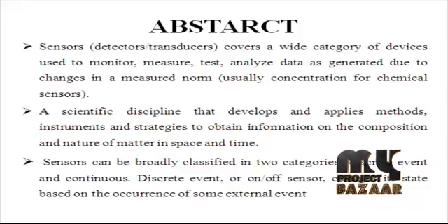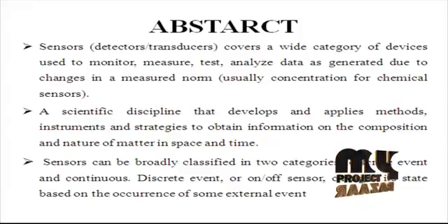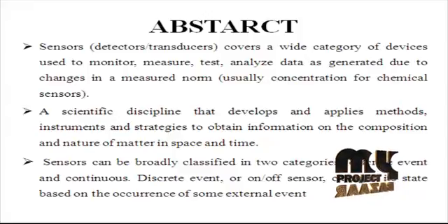Micromechanical resonant devices based on the mass loading effect are a promising platform for miniature chemical sensor systems. They offer superior sensitivity, high resolution and a wide range of applications. These devices include thin film bulk acoustic resonators, surface acoustic wave devices, capacitive micromachined ultrasonic transducers and micromechanical cantilevers.